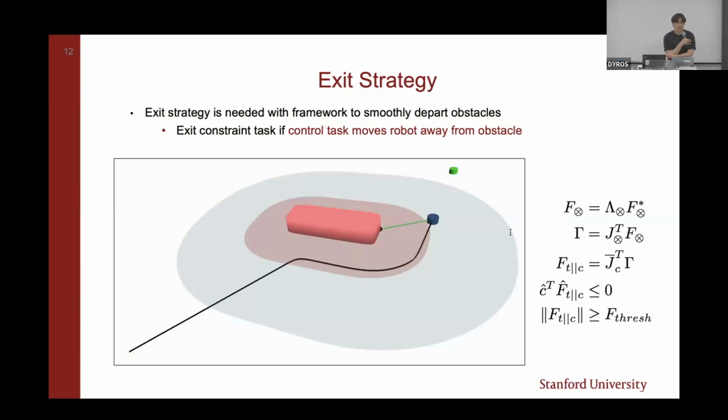So for a general robot, we achieve this by projecting the control torques onto each constraint direction using the dynamically consistent inverse Jacobian. So that's on the right, J bar.